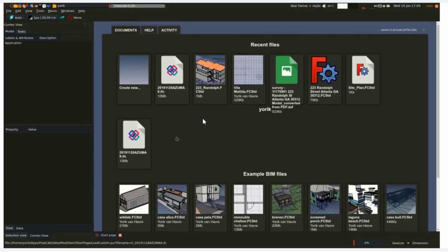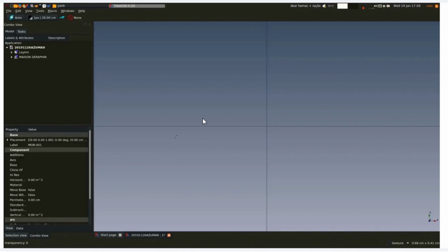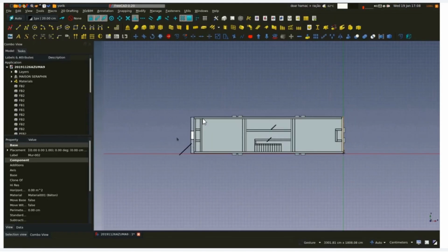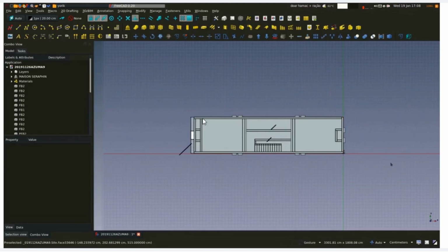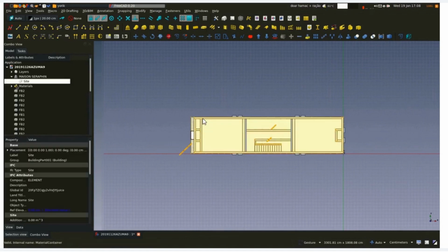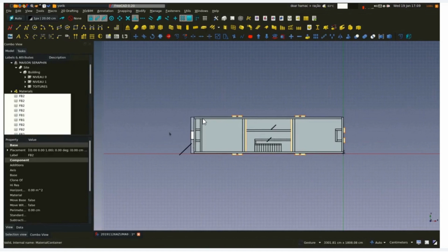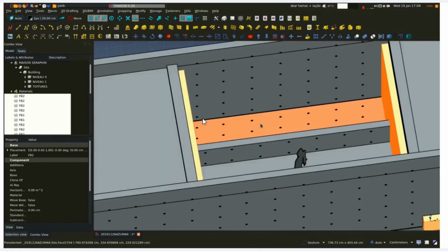Okay, we're now going to perform some cleaning operations on our model. I am now opening the IFC model the normal way in FreeCAD, that is using file import, which doesn't deal with the Python console, but directly imports the objects in the FreeCAD document. You see, we have a couple of objects that are not inside the level structure.